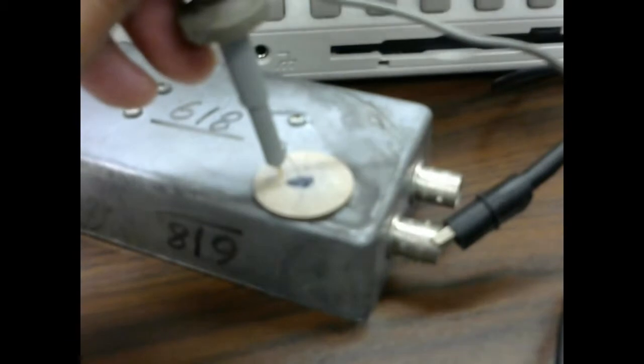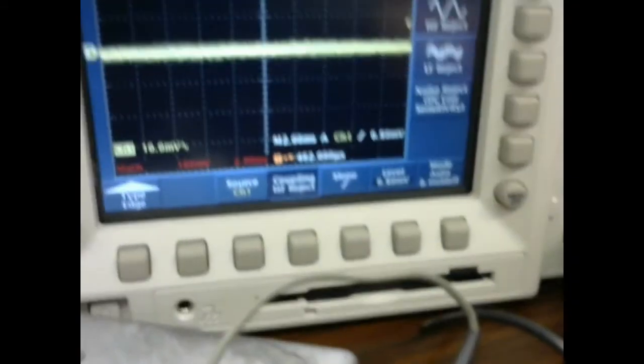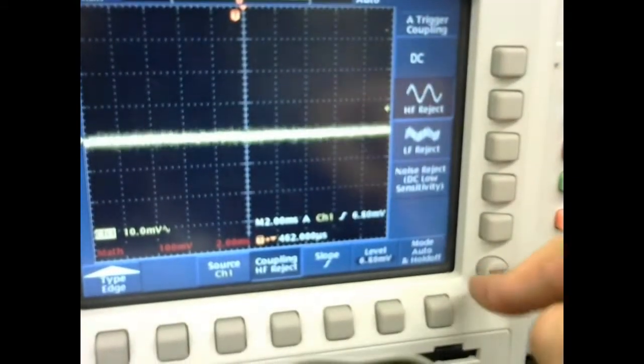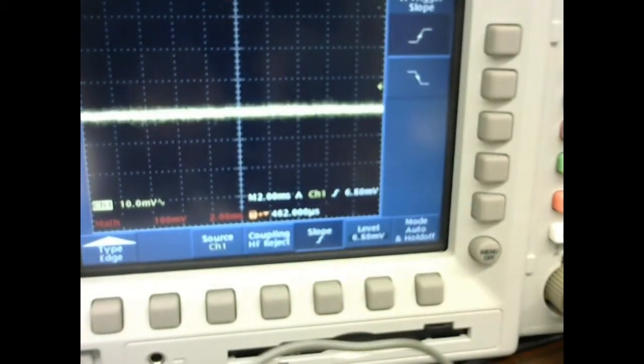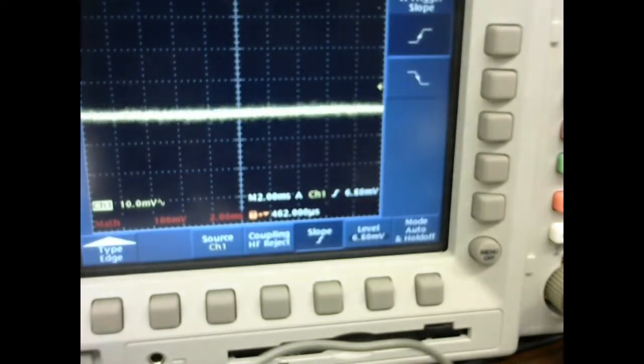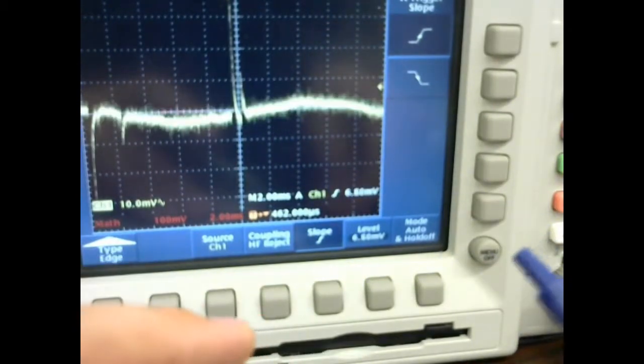That's probably not going to be the case here. The voltage developed was much more, and so basically you can hit it. Like I said, the trigger is an important thing to consider. The slope, whether the voltage is going down, it's going to trigger when it's going down, so you should be careful. But I think I just showed it, and we'll do it again to make it even more clear to you.